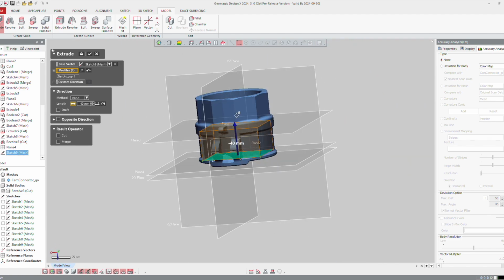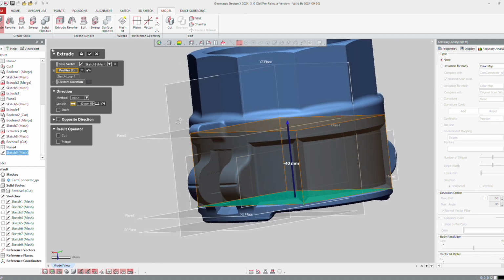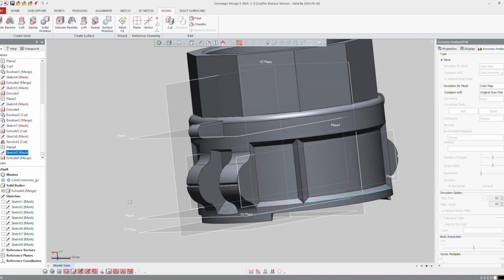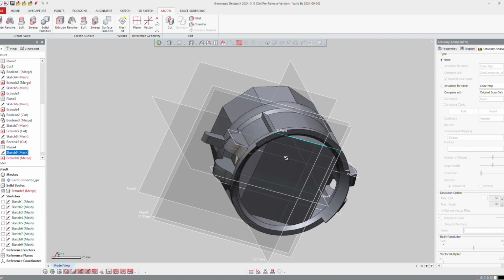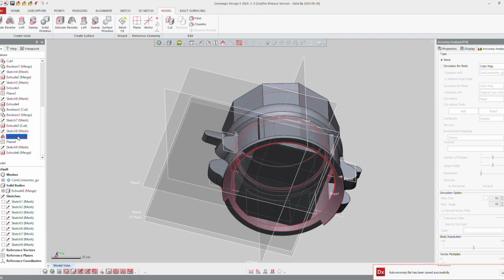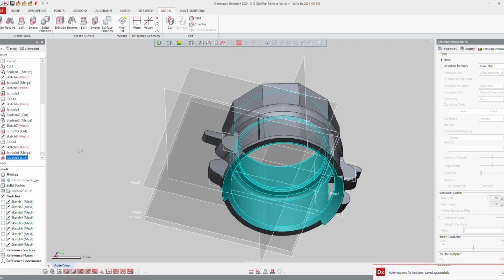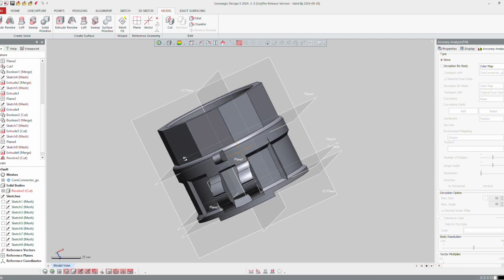But you can see that while I'm doing that, I will have a little issue on the part. I will merge that, okay, because now if I display my part, the CAD, I got my square up here before my revolution. So it's not empty. So again, it's a CAD software. So my revolve removes everything inside. I can click here and move it down and reorder. And now I got it well defined.